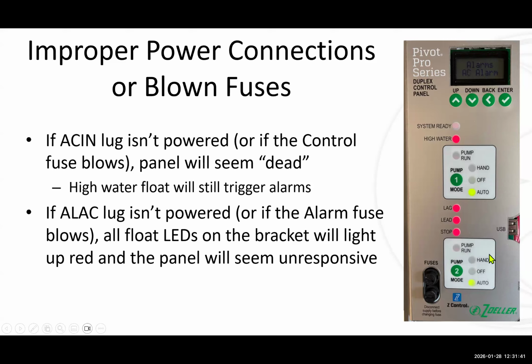Again, it will seem unresponsive, and you won't be able to change anything or do anything. But that's the panel's way of saying, "Hey, look, something isn't right." You either have a fuse that's blown or something's going on. But it will be an alarm telling you that something's going on. Again, the idea here is we want you to know when something is wrong. We want it to be obvious when something is wrong.